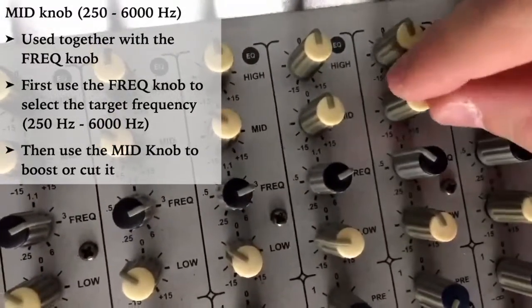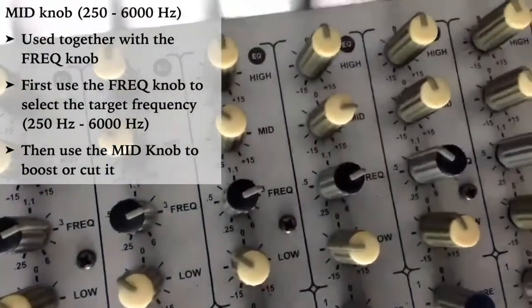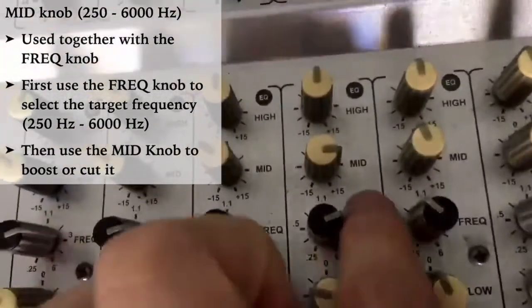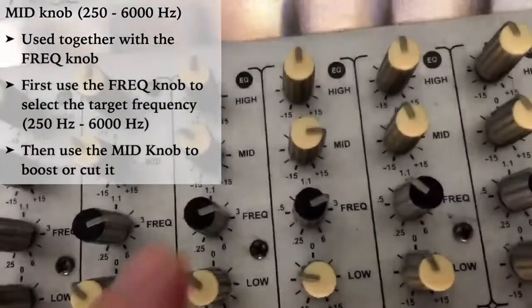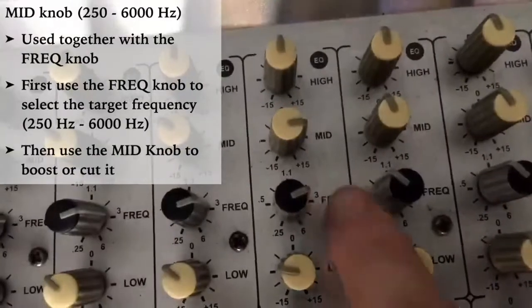For example, I'm going to boost the mid. I'm going to boost it up like that, okay? So I've already added maybe 10 decibels. This one is plus 15 and minus 15, the decibels. So now I have increased 10 decibels at a frequency of 3000 Hertz.